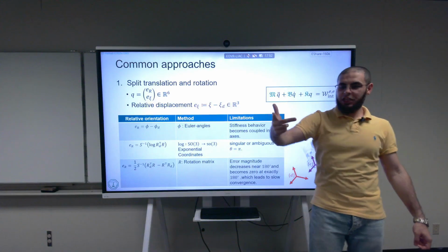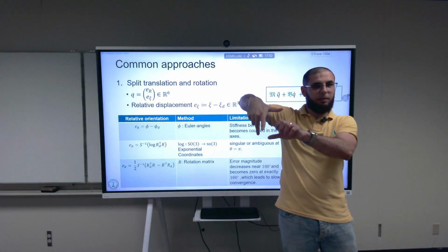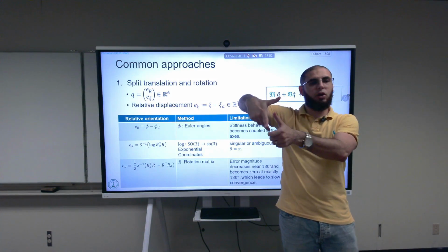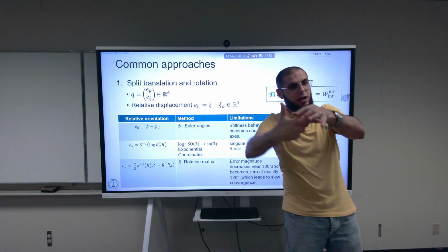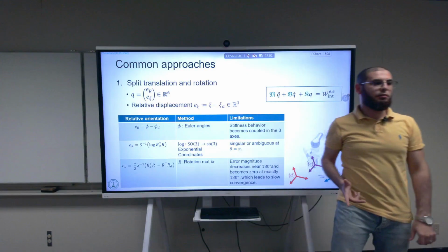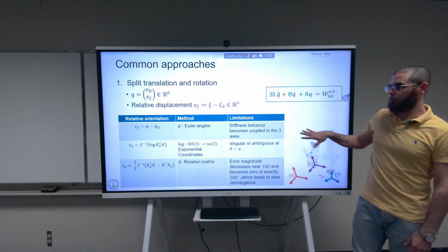So when I change the orientation of what the robot is doing and apply the error, I get different spring behavior. The spring matrix depends on how you're moving. That's why it's coupling them, and that's why you need to look at a little bit of math to get convinced.